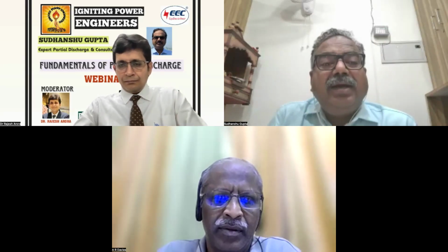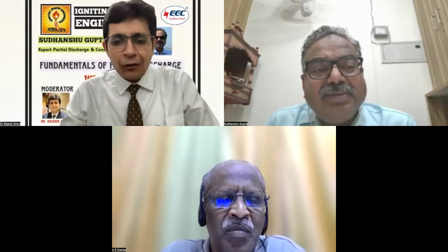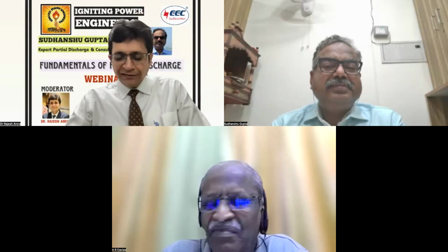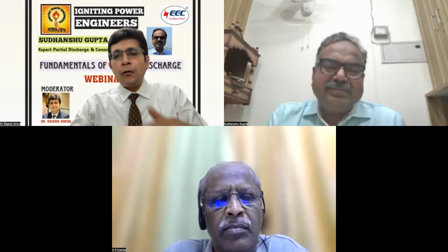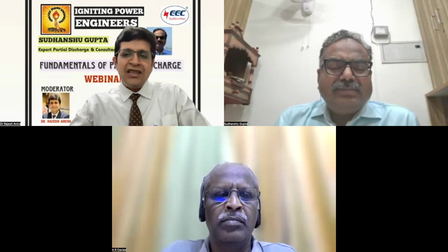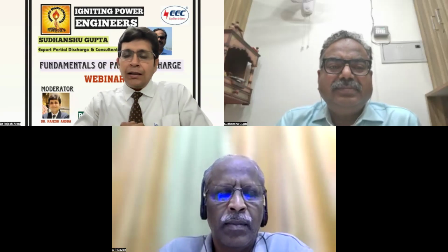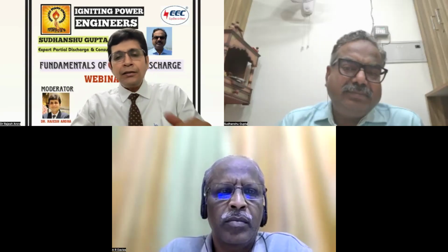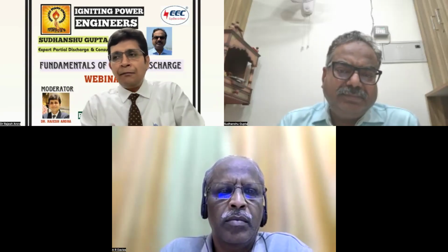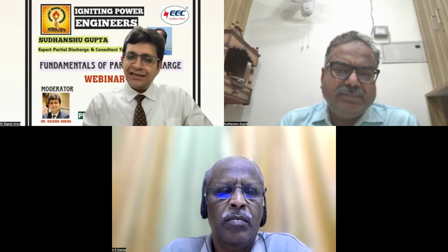Rajesh, you wanted to ask something. On behalf of the utility, I can answer your question. For a transformer, it is on a need basis. When you are getting a rate of rise in acetylene in your DGA and you are not able to identify the fault, then you go for partial discharge testing of your transformer. That is not based on any frequency; it is based on the requirement and is linked with your DGA analysis.